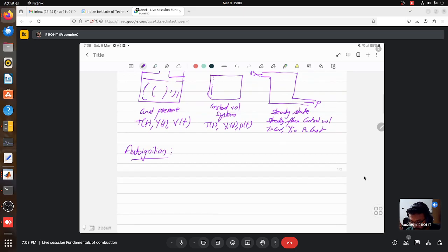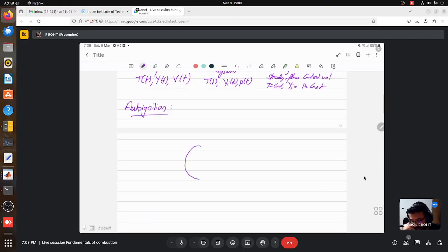When you have a fuel-air or fuel-oxidizer mixture in flammable proportions, injected into, say, a small spherical chamber, with your pressure regulators and thermocouples measuring the chamber temperature, we call the chamber temperature Tc at which there is a rapid rise in pressure.